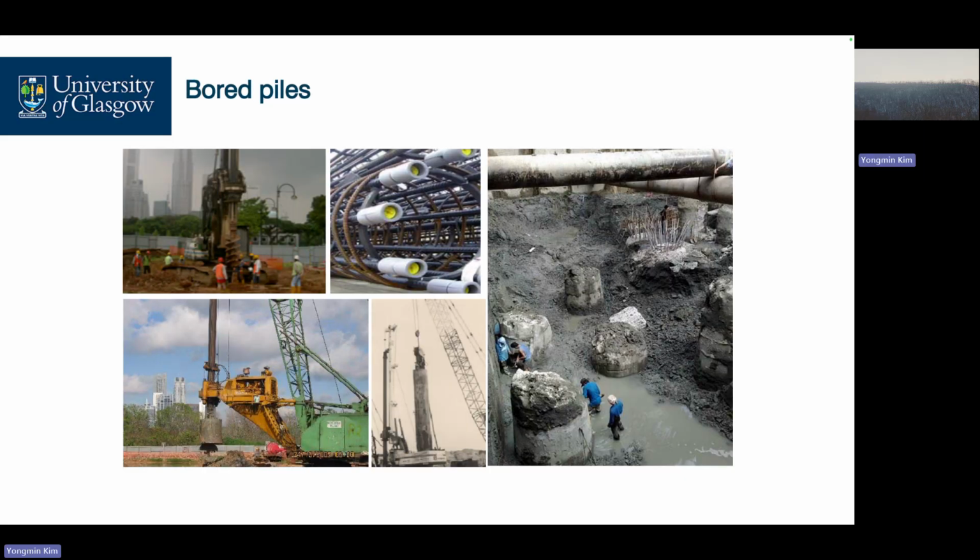This is the fully drilling machine. The screw, and then this is the bored pile cage. After boring, we put it into the hole, and then pour concrete. Different lengths, different. I mean, right after our pouring and curing the bored pile, we cut it out and then level them all to the same heights.